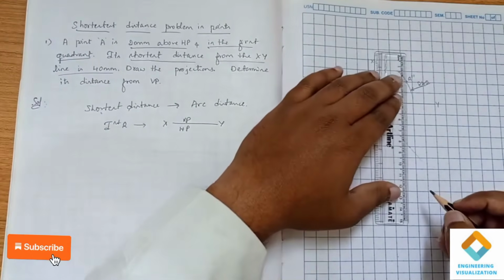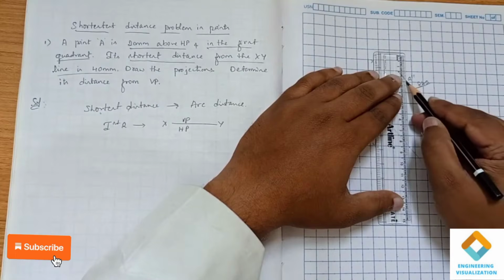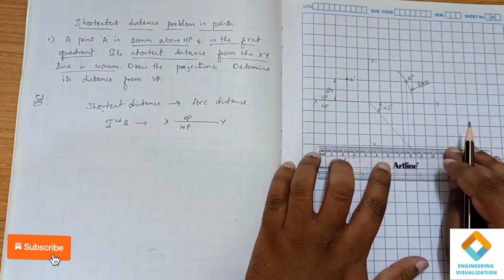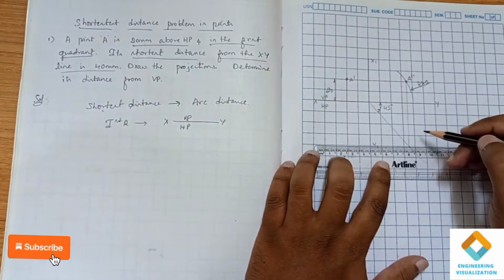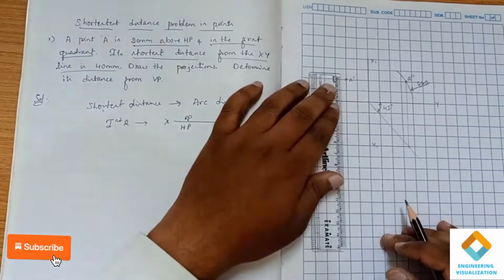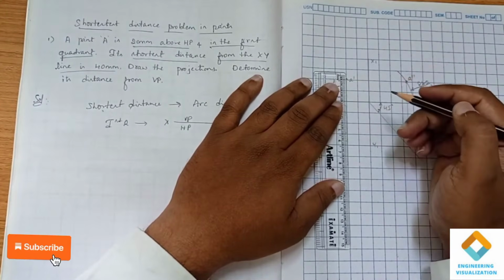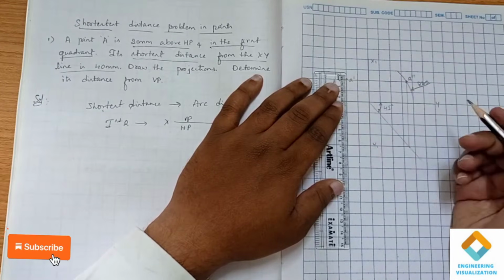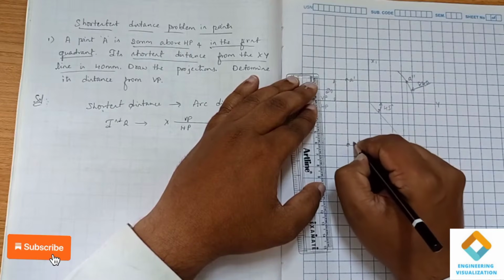Now we draw from this side view a vertical line until it touches the 45-degree angle line, and from this point you draw a straight horizontal line. You know that the front view and top view are in a straight collinear line, so we will be drawing a straight vertical line here. Okay, where these two lines are intersecting, this point is our top view.